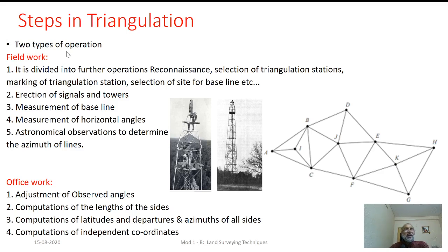So, one must have carried out the reconnaissance related to these surveys. Here the fieldwork, as you see, is divided into reconnaissance, selection of the triangulation stations, marking of the triangulation stations, and selection of the sites for baseline measurement, and these things we have already discussed. One of the important concepts is related to the erection of signals and towers.